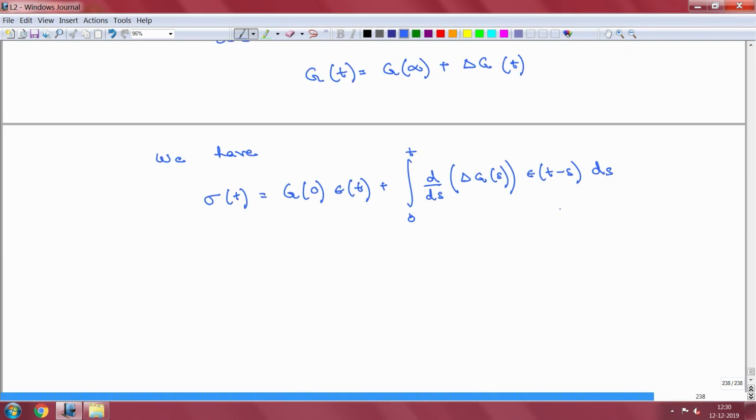So, what is it that we are really looking for here? Now, the strain is the input, and we are trying to figure out the expression for the stress from this, given that you know the functional form for the stress relaxation function. So, we now have to assume some form of time dependence for our strain here, which you can take as either sin(omega s) or a cosine, but for generality what we will do is just go into the complex formulation. That just makes life easier for us.